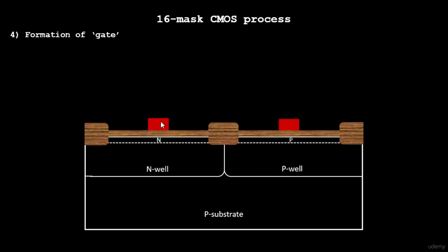So now you see how the fabrication steps are closely related to your threshold voltage, and threshold voltage decides the turn-on voltage of your gates, which in turn decides the functioning of the gate. So these are all interrelated. Okay, so let's try to look into how we do that. We are going to control the oxide capacitance and the doping concentration through the further steps.